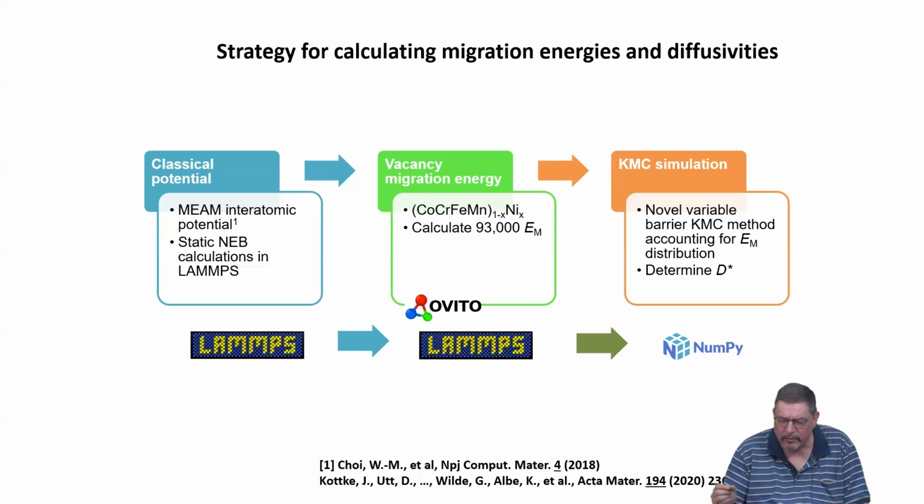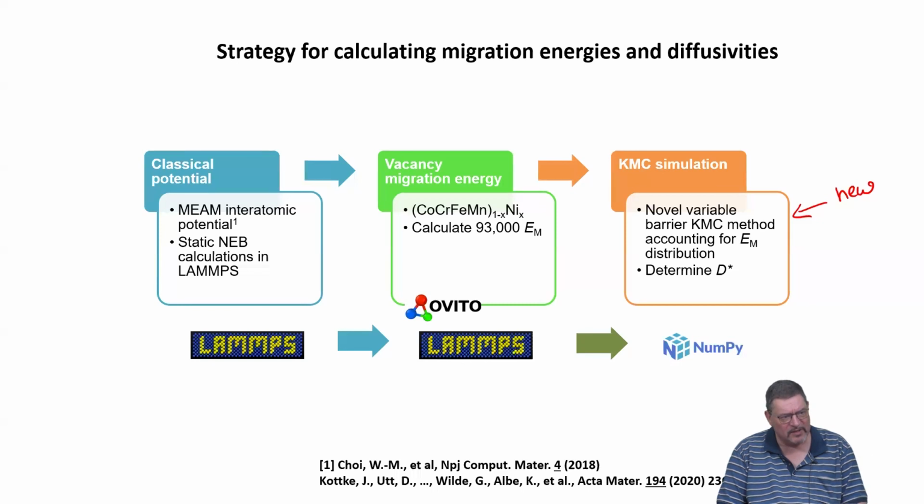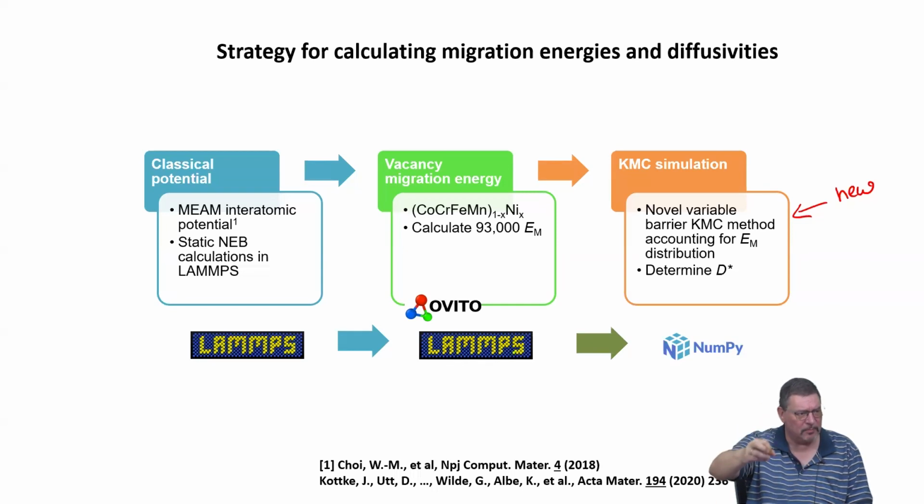The important point which they added here is that they used kinetic Monte Carlo, KMC, calculations where they basically took into account that in a disordered alloy which has many constituents, each atomic jump would have its individual barrier, because it depends on whether this specific atom, let it be nickel, has manganese as a neighbor or cobalt as a neighbor. And this was really taken into account here for the first time.